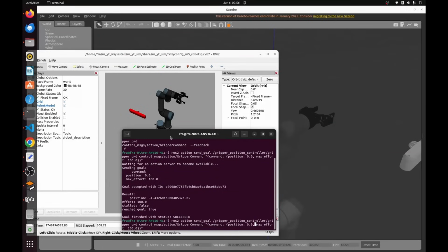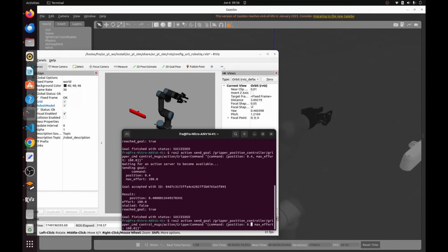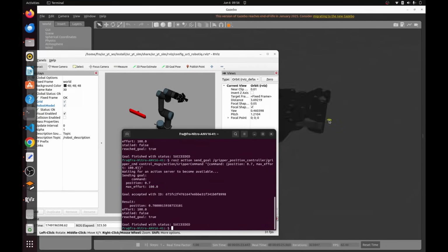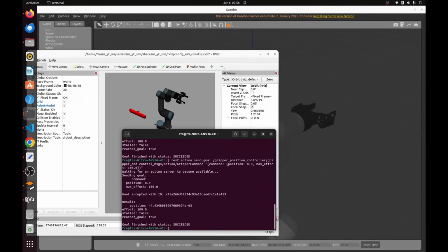Hi roboticists, finally today we are diving into a key topic for anyone looking to break into robotics. In particular, we are going to install and configure a robotic gripper as an end effector of our Universal Robot 5 and simulate it in Gazebo, complete with its controllers. I will walk you through exactly how to use a dedicated GitHub repository, showing you which files are essential, how they fit together, and how we will need to modify them for our needs and in order to simulate in Gazebo.